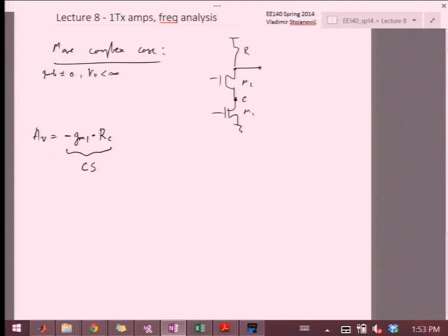And I know that, so if I draw things out, this is R out 1. This is R in 2. This RC will be equal to R out 1 in parallel with R in 2. That's the total that transconductor sees as load. In this case, our R in 2 is just like our RL, and our R out 1 is just like the internal output resistance of the first stage amplifier. And then I have CG.